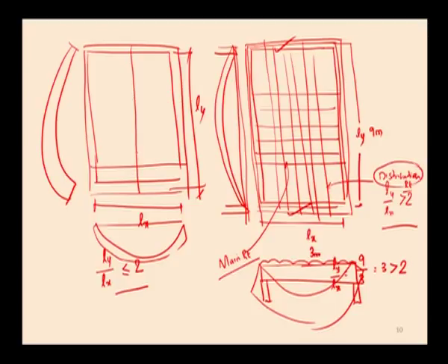These two reinforcements are called main reinforcement, but it is not like in the case of a one way slab. In the case of a one way slab, it is spanned along only one direction, and the reinforcement which is provided in the perpendicular direction is called the distribution reinforcement. It is not a main reinforcement, it is a minimum reinforcement. It is only to distribute or keep the main reinforcement with the proper spacing and also to avoid the cracks which are developed.